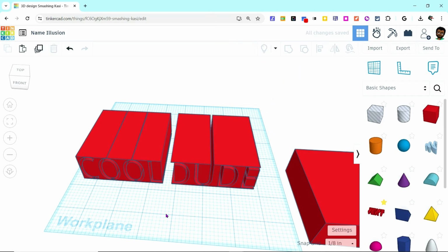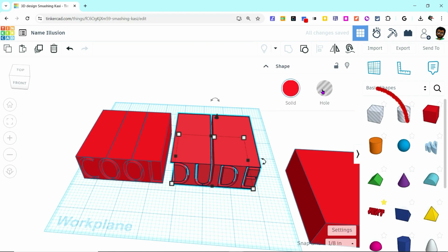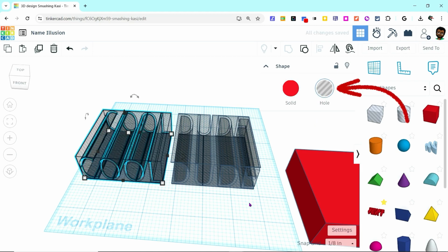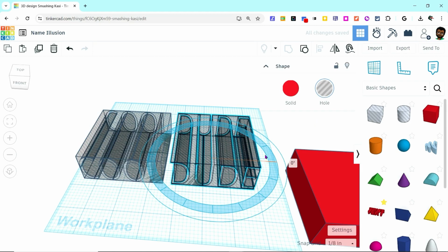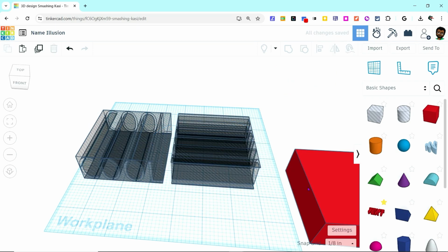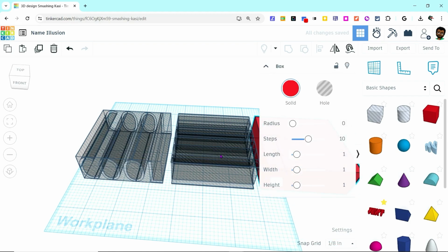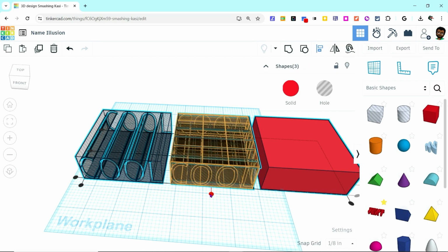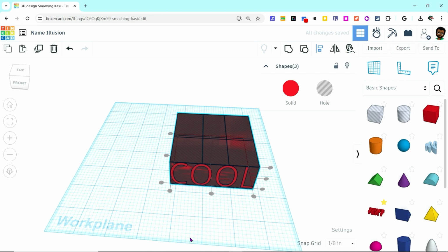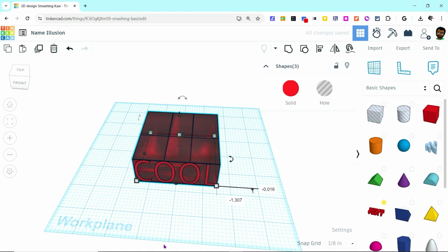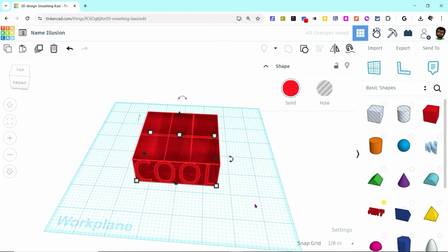All right. Now, time to make it a hole. Same as before. Hole, hole. And I want to take this one and turn it 90 degrees. All right. Move this box into place. And I want to get them all aligned. So all 3 shapes will be aligned. Middle and middle. Great. Notice again that all of the handles will be grayed out. Put this in the middle a little bit, and I want to group them.